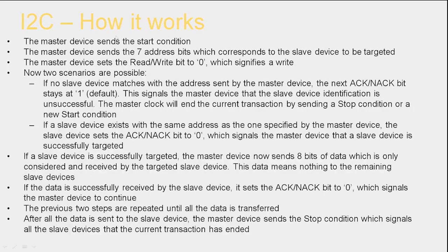So this is how it works. First the master device sends a start condition. Then it sends the 7 address bits or 10 address bits of the slave device to be targeted.